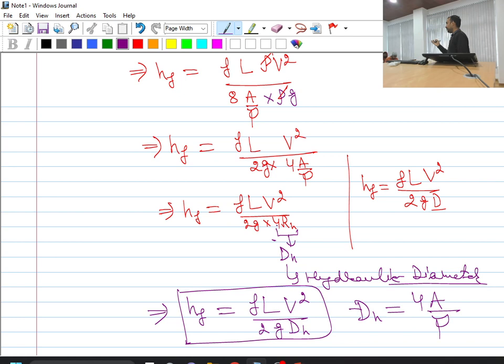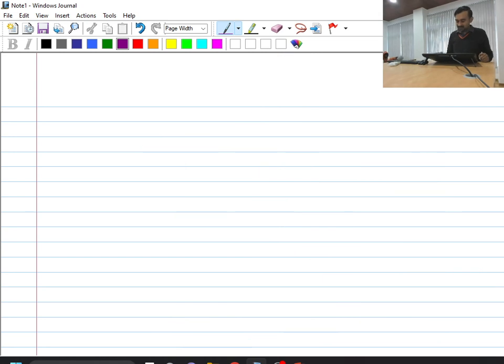So this is the generic idea. Whatever I have studied till now for the circular duct, the same analogy I can apply for non-circular ducts. The only correction is that in place of diameter, I have to use the hydraulic diameter of the duct. Is this point clear? We have made this basic analogy based on the geometry and the force balance along the streamwise direction. Now we need to check this hypothesis by testing different non-circular geometries: if we simply substitute the diameter with hydraulic diameter, can we correctly calculate the pressure drop or head loss? That is what we want to ensure now.